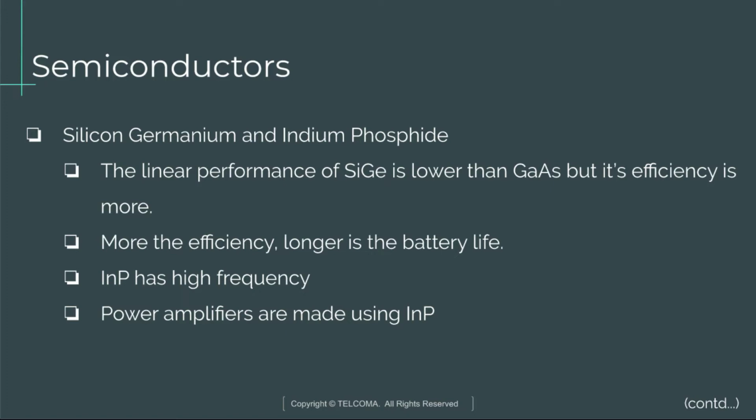The driving force behind InP is high frequency, specifically performance at millimeter wave frequencies, that is greater than 40 GHz. InP has amongst the best low noise performance of any material today at very high frequencies. InP can also be used to make power amplifiers, of course, at millimeter wave frequencies, though high power isn't all that high. Unlike SiGe, however, for the time being, InP is still relatively expensive to manufacture.